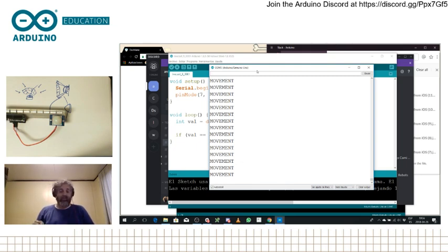The difference between the Parallax one and the other one that I have here, as I said, is that the Parallax one is ready to use. And this one might or might not require you to include a pull-up resistor. Also, since this one doesn't have a pull-up resistor, because it's an open collector, you could use it to directly trigger a light, while the Parallax one will most likely require connecting to something else to trigger the light. Okay, so this is a very simple example.